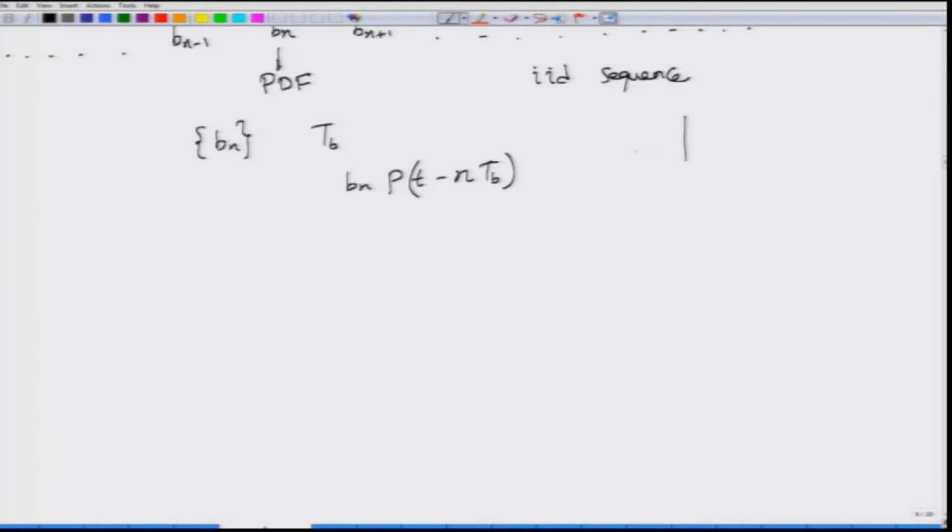From your signals course, you might know that if this is a basic pulse shape, with time t, and this is TB/2 and this is -TB/2, here I am showing you a rectangular pulse. If you are fancy enough, you can have a different pulse, it does not matter, but the duration of the pulse has to be within 1 TB units. Then, if this is P(t), what would be P(t - TB)?